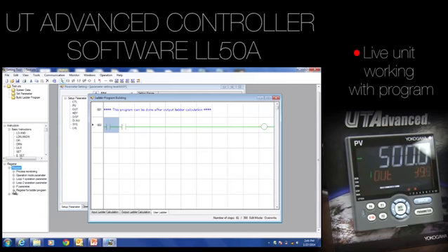In this case, special registers, timers, counters, data registers for storing mathematical equations or results of math equations, status registers for bit inputs, constant registers for certain parameters we may need for calculations, things of that sort. I'm not finding what I'm looking for here. Special relays, there we go.